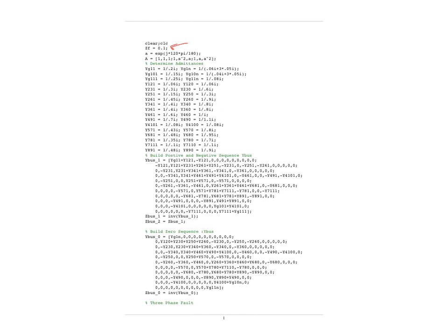And so you'll notice I have my A, 1 at an angle of 120, my major A matrix that I encourage you to memorize in your calculator. And then I actually specified all the positive sequence. So you notice that I have a 1 all at the end here. These are the positive sequence admittances. So those are all defined here. And then next to those I have those negative and zero sequence admittances.